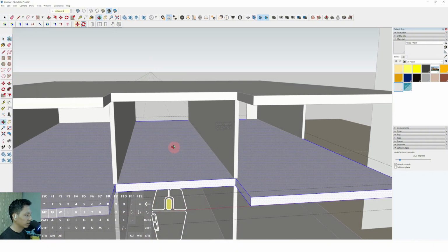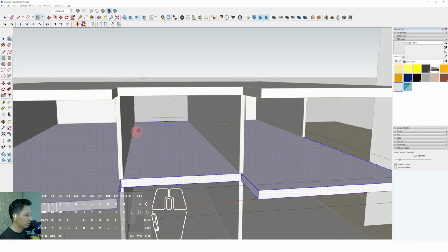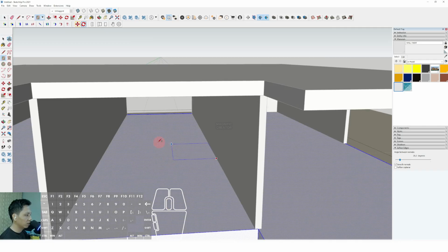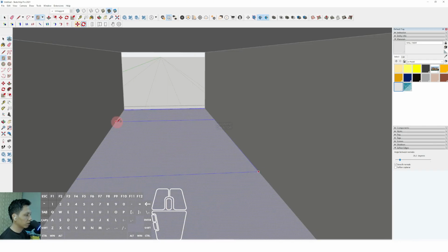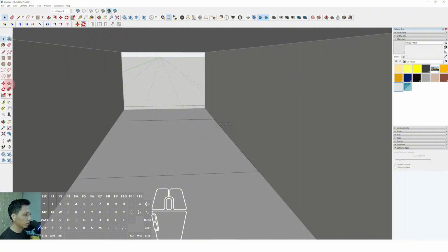Okay, we can imagine that it has a void. We can imagine that it has a void area in here, approximately in this position. Then we have to push it down using the push tool. Okay, I will repeat. We can use the rectangle, click from this position and place it to this position.